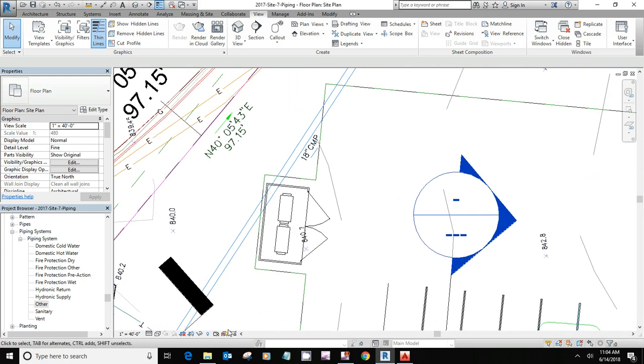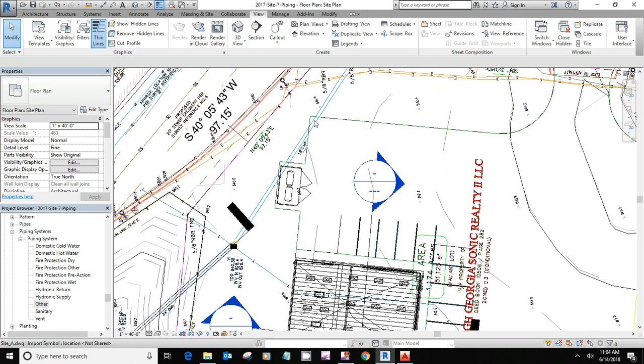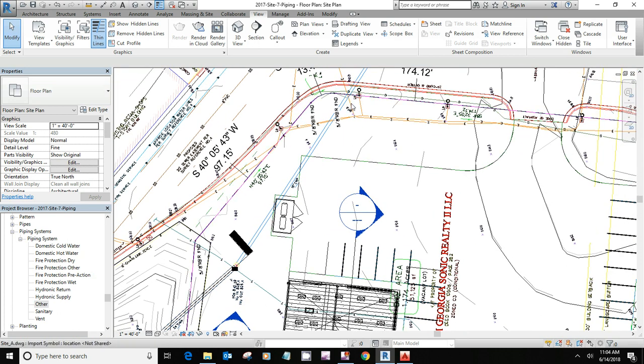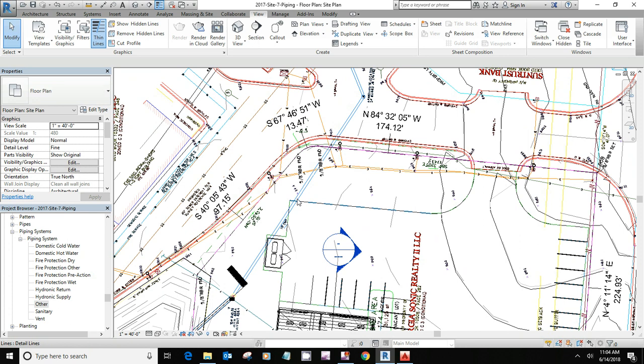Now this one here, we're just going to draw it from the junction box down, and we'll do an 18-inch difference in elevations. So my invert in at the catch basin here was 14.85. That means my elevation up here will go 18 inches higher. So that would be calculator, minus 1.5, 13.35.